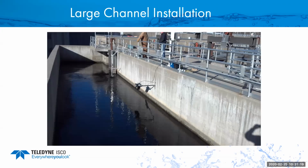You can mount multiple lasers in a channel like this. So we can mount technically up to 9 lasers on one Signature flow meter. Realistically, you can do 3 comfortably. But in some cases, in the UK, they're doing 3 on channels that are over 5 feet wide.